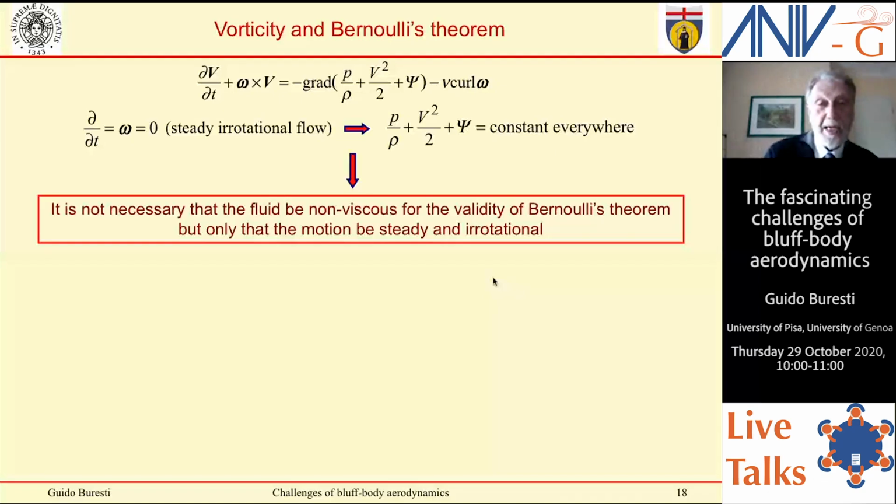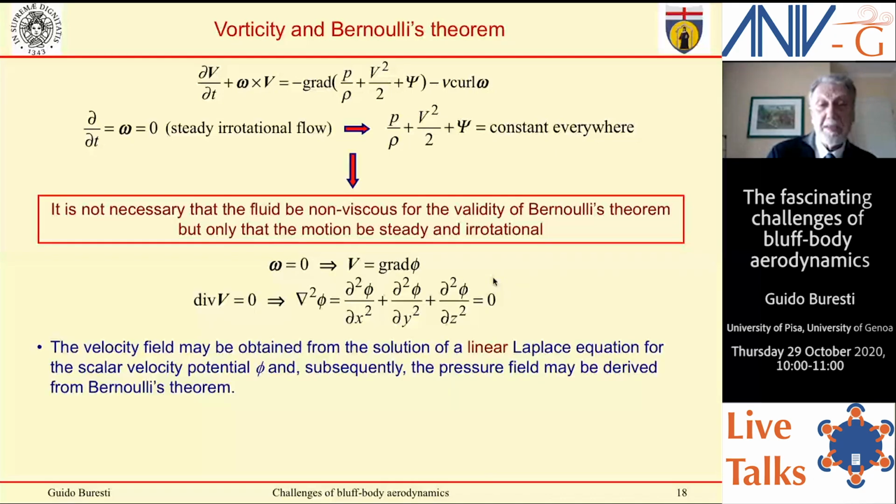Now, what happens if vorticity is zero? Velocity may be expressed in terms of a scalar potential, and the continuity equation becomes the Laplace equation for the velocity potential, and you obtain velocity, and then from Bernoulli's theorem you get pressures.